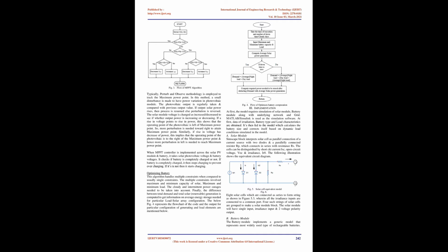The distribution system generally begins at a substation, and is fed by multiple sub-transmission lines. Each substation is built to supply primary feeders. Most distribution feeders are branched, i.e., electricity flows from the substation to the customer. An average power distribution system is comprised of a distribution substation which has a few feeders. Each of the feeders consists of a three-phase primary main feeder which branches laterally to two-phase or single-phase. The power lines can be over the ground or below it, depending on viability and requirement.